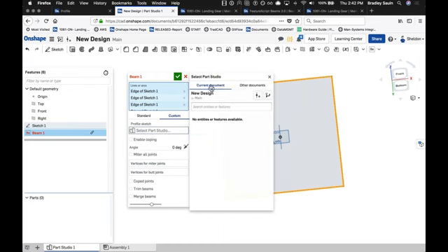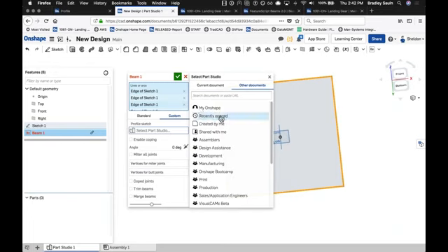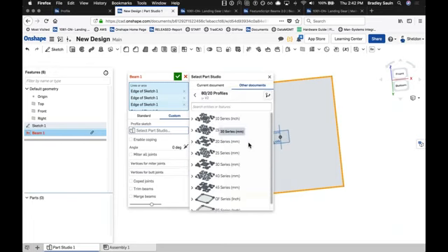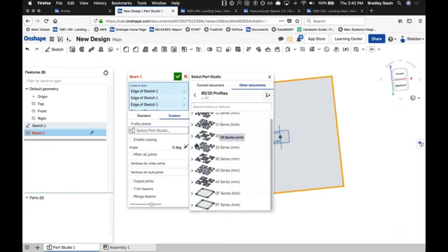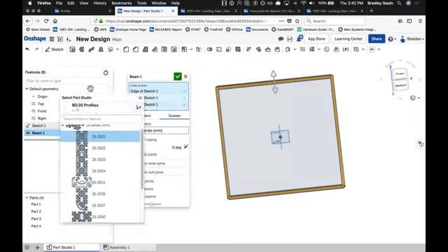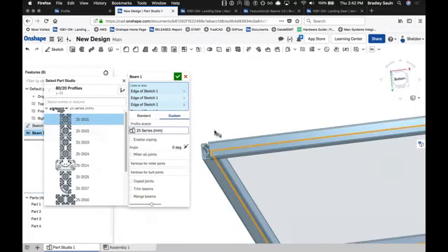So you can open up and search either the current document for other sketch profiles, or search any of the other documents within Onshape. So we do have a public document of 80/20 profiles. These are just sketches done from the top plane about the origin point. And now I can specify a specific 80/20 profile used instead of just the limited set of standard options in the beam tool as a whole.